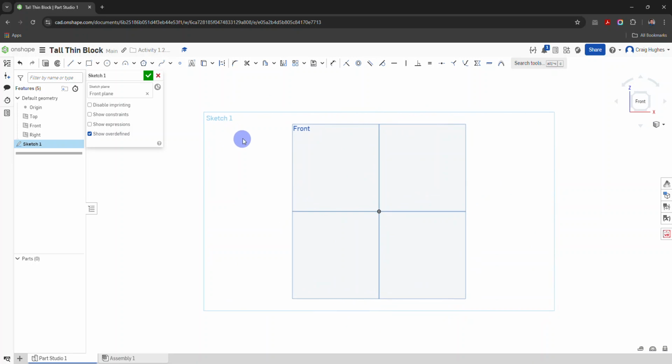to turn that normal. Notice how the principal work planes are still visible. Go ahead and right click on one of the names over in the browser for the top, front, or right work plane and select hide all planes.